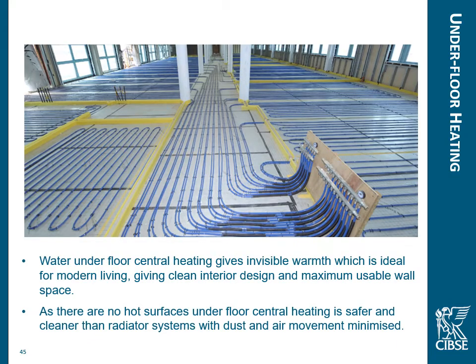We can see how the pipework is set out in our commercial buildings there. We've got a similar sort of situation with domestics as well. But one of the good things with underfloor is that it gives us good controllability of individual zones. So we can see on the picture there, these may be individual rooms or offices or classrooms or workshops or things like that. Each room can be controlled individually via a manifold.